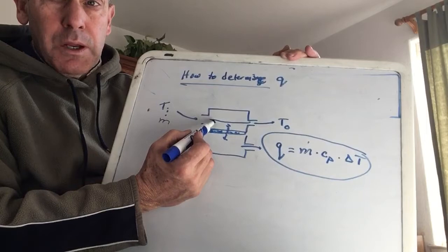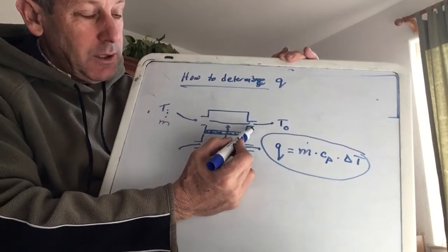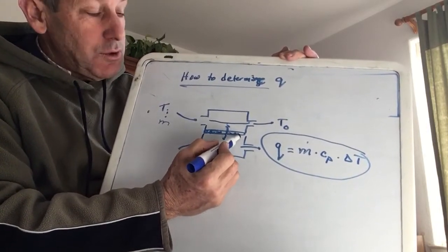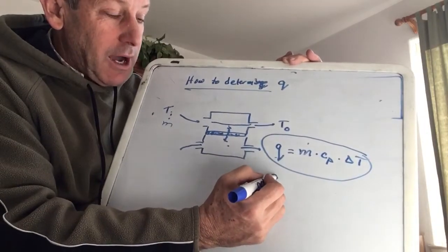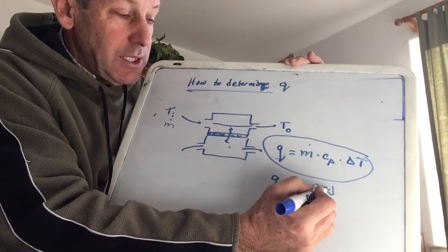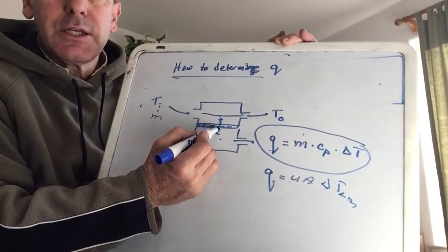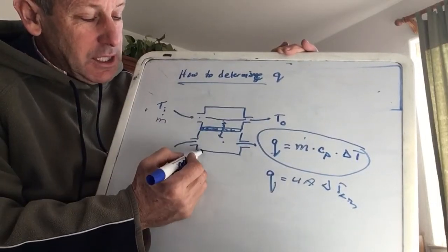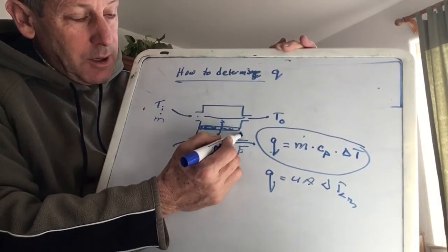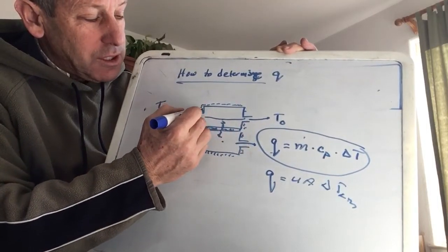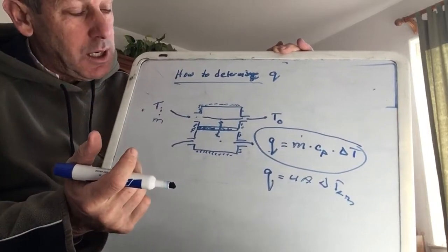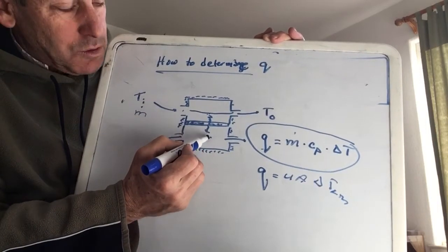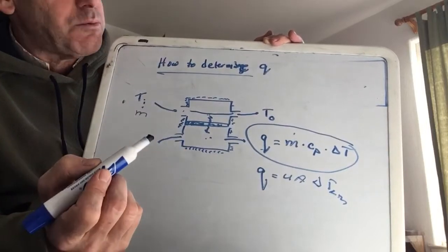If you think about it, we have Q, or heat transfer, for one fluid, and we have heat transfer for another fluid. Well, the heat that comes out of this fluid goes to that fluid, so those two Q's need to be the same. Finally, we have our Q equals UA delta T log mean, and that's the heat transfer that actually gets through this plate. How does that compare to the heat transfer that gets out of, say, this engine oil? Well, if this heat exchanger is pretty well insulated, and you can assume that for all the problems that we do, and of course it's not a bad idea if you're using heat exchangers to insulate them, then the heat that gets out of this fluid will be the heat that goes through this surface, which will be the heat that goes into the other liquid, so all three Q's are the same.